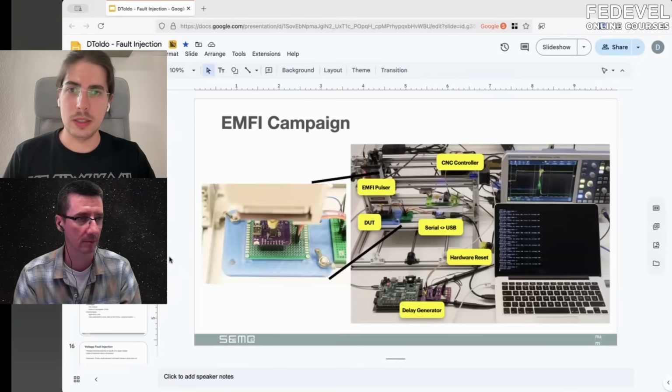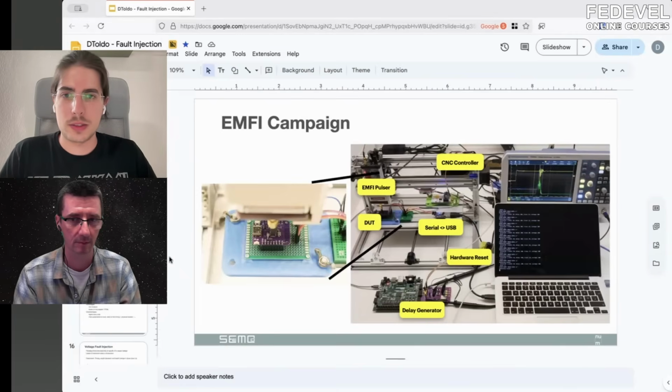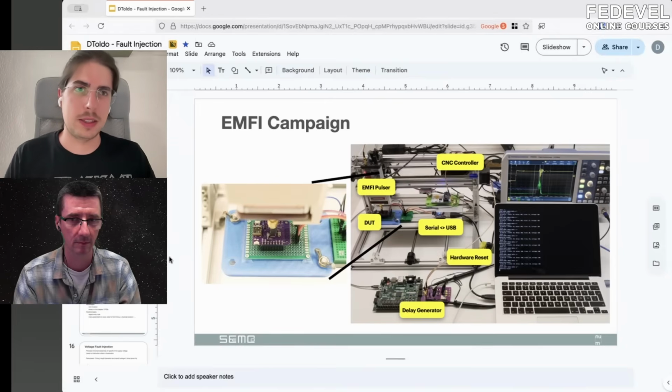Sophisticated attacks use high power supplies and signal generators, and they don't use FPGAs and stuff like this at all. So they use dedicated lab-grade hardware to get even more precise, usually because of the timings, but also to get strong high voltage pulses for fault injection with electromagnetism.